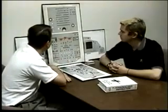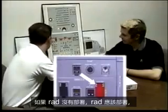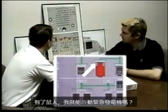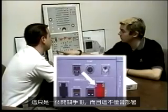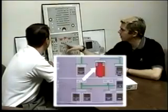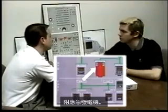Ram air on. You told me on the emergency electrical panel that selecting ram air on, if the RAT didn't deploy, the RAT should deploy, and I would get the emergency generator. Would I get the emergency generator with that ram air on? No, this is just a manual on switch, and this is going to not only deploy the RAT, but it's going to open up a second valve that'll allow the emergency generator to be powered. Over here, we're only opening one valve when we do it, and it just allows the system to pressurize the blue system, but has nothing to do with the emergency generator.